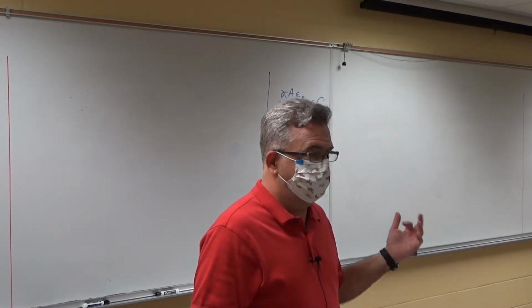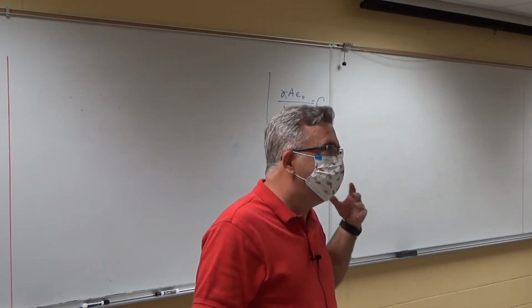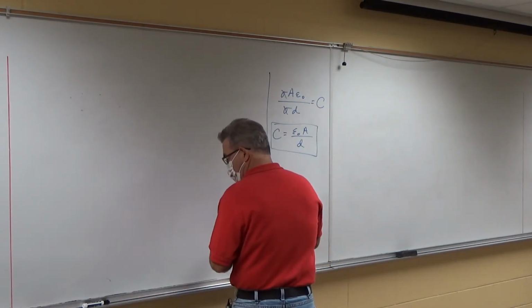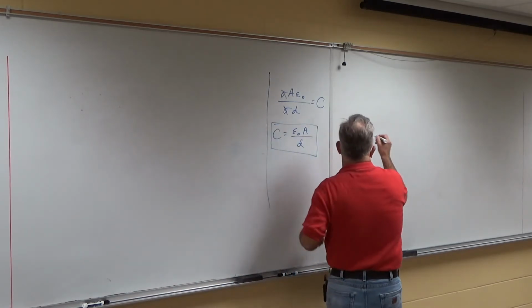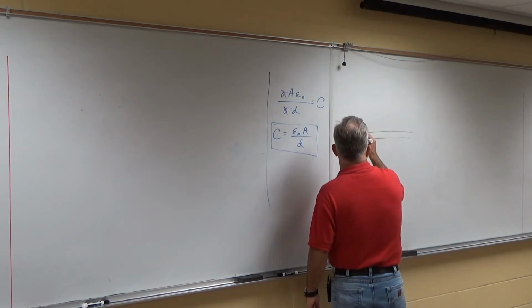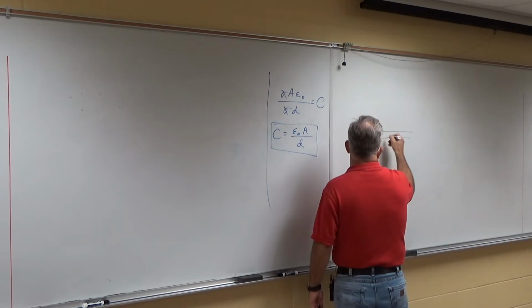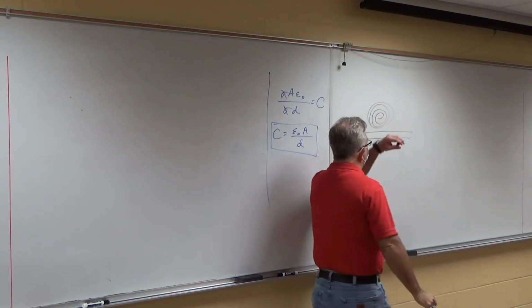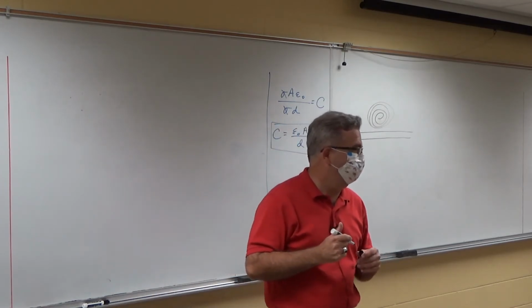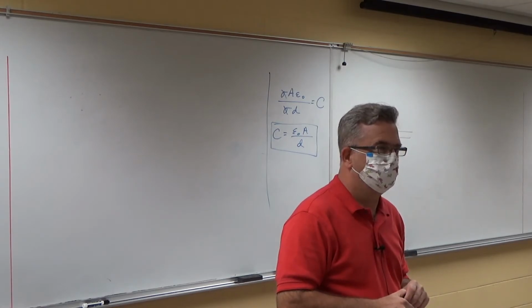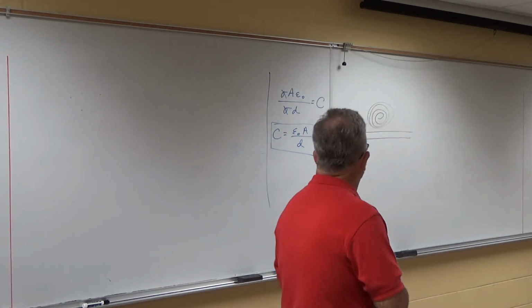Another way that they make fairly, well, it's not huge capacitance, but they take a film like foil. I'll have a foil, and it'll be very, very long. There's also a dielectric, but they take a foil, really, really close, and then they just roll it up and stick it in a cap. Those are spiral wound capacitors and so forth. They're wrapped.